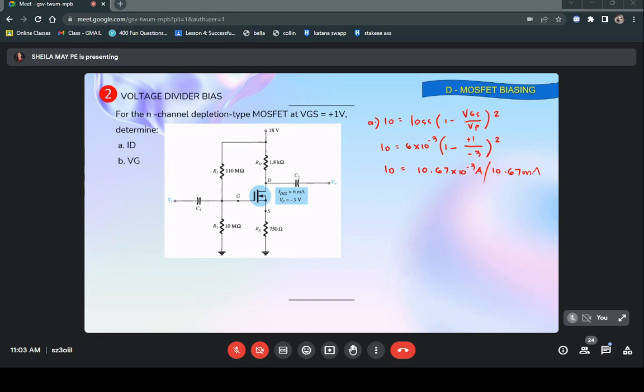e-MOSFET biasing. For e-MOSFET class, we have two also, the drain feedback bias, or the feedback biasing, and the voltage divider. So for a popular biasing arrangement for enhancement type MOSFETs, we have here drain feedback bias, and a direct connection now exists between the drain and the gate, resulting in, okay, we have here the biasing arrangement for our drain feedback class. We have RD, RG, our E-MOSFET, and we have our source without any resistor.